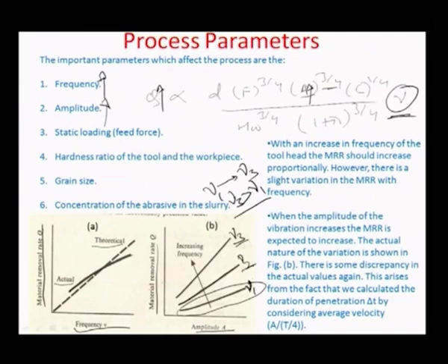So as you increase the frequency, the overall material removal rate for different frequencies, with amplitude, would have a linear increase. We have already studied this aspect, the feed force, where you saw that there is a grain crushing effect, and some other trends that can be useful are related to what would happen, for example, with increasing amplitude and feed force.